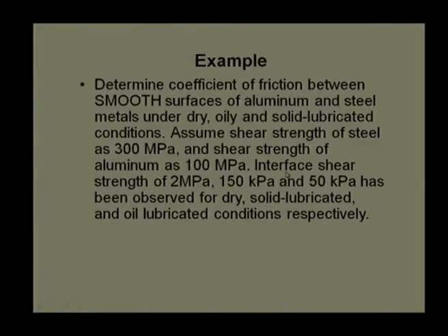Then, in addition, we have data related to interface shear strength, which is 2 megapascal, 0.150 megapascal, and 0.05 megapascal for the dry, solid lubricated and oil lubricated conditions. From this example, it is clear that the oil lubricated condition will give the minimum shear strength of the interface, and dry contact will give the maximum shear strength of the interface.